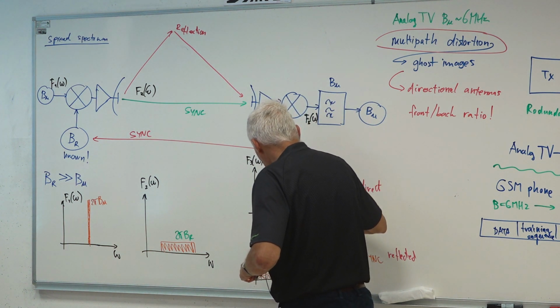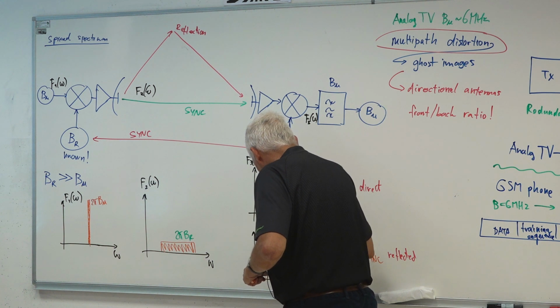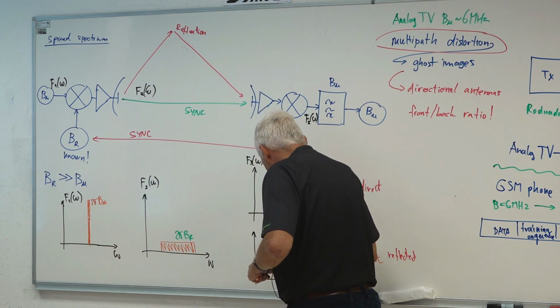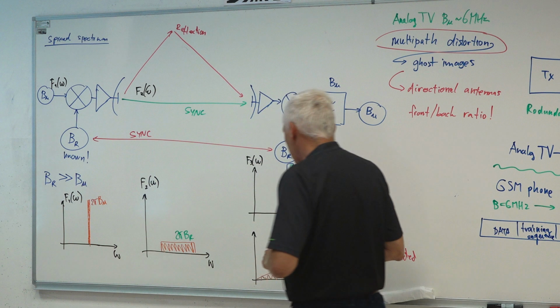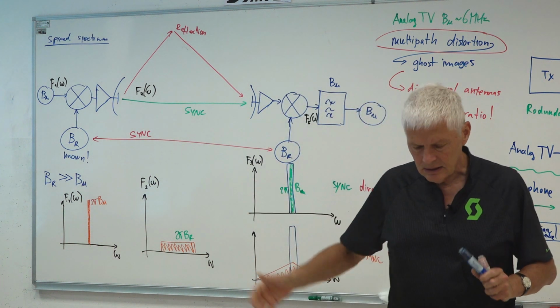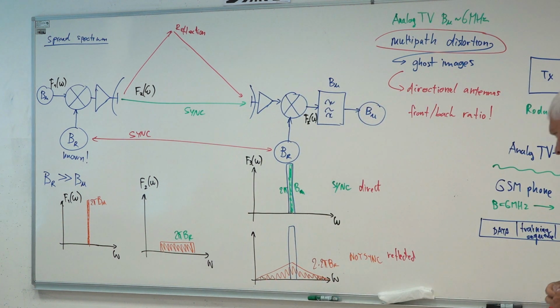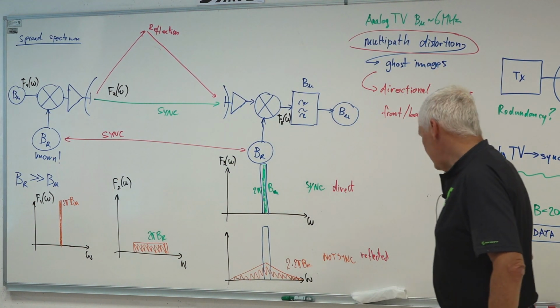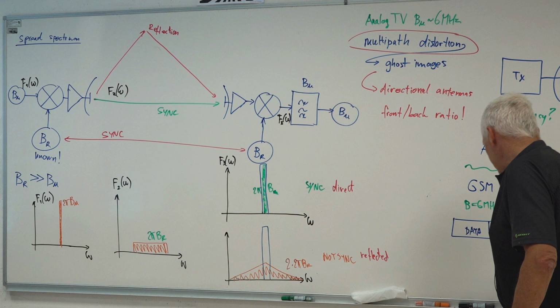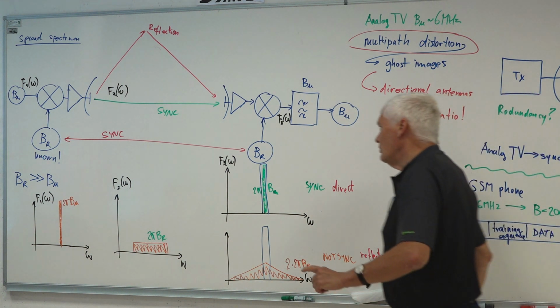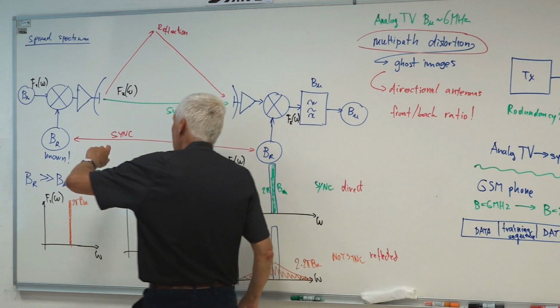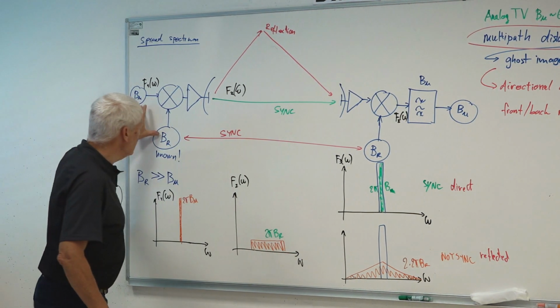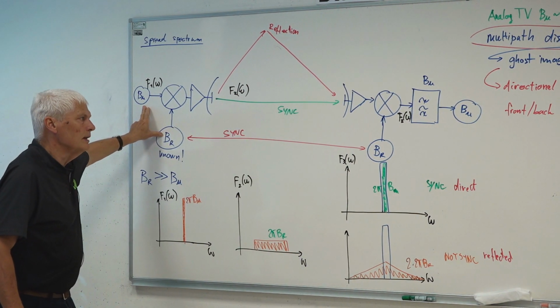our desired signal, and we are also left with a small amount of interference, but this interference is very small because it is spread across a wide spectrum. So just a small amount of interference makes it through this filter here. So I can improve the signal to interference ratio a lot. My improvement is comparable to the ratio of these two bandwidths here.